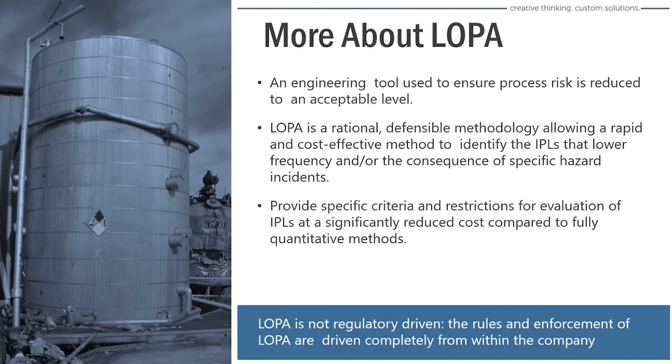Again, with the PSM standard and the risk management plan out there since the early 90s, we've gone through multiple iterations of PHAs. If you revalidate a PHA where the process hasn't changed much, it gets kind of rote. Folks say, oh, it hasn't changed much in 5 years, so we're not going to look at it closely, and it becomes more of a paperwork exercise than an actual risk assessment.